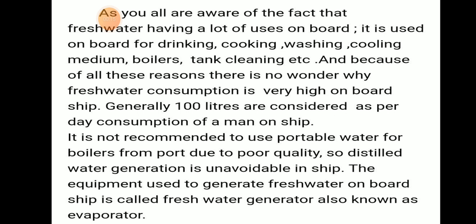We all know that onboard ship we are using fresh water. It is used on board for drinking, cooking, washing, cooling medium, boilers, tank cleaning, etc. For all these purposes we need fresh water, and there is no wonder why freshwater consumption is very high on board. Generally 100 liters are considered as the per day consumption of a man on board ship.